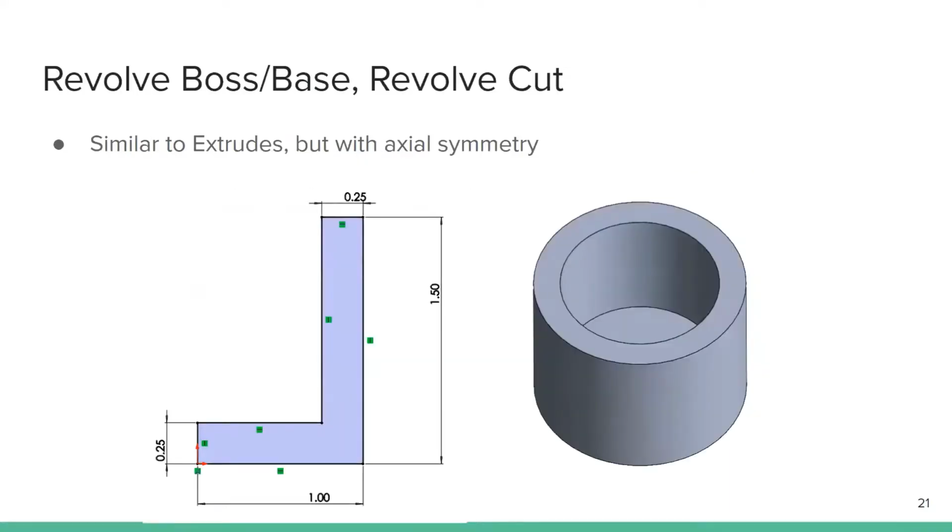Awesome. So Andy talked a bit about this earlier, but the Revolve tool is definitely one that blew my mind when I was first learning SolidWorks. It's not initially intuitive, but it's so incredibly powerful that it's something you want to start getting your head around. It basically allows you to create really complex geometry from just a single feature, so it's super useful.